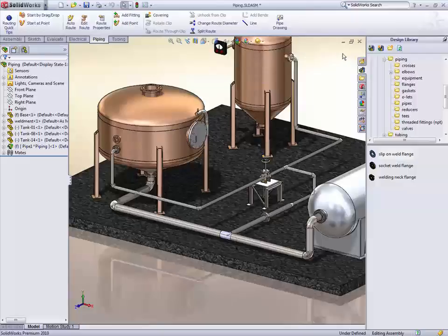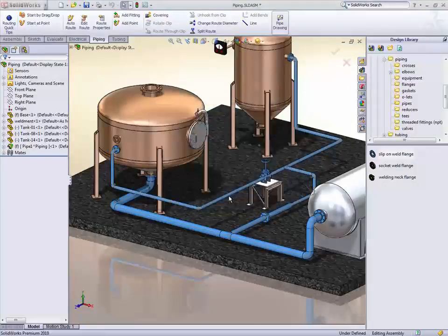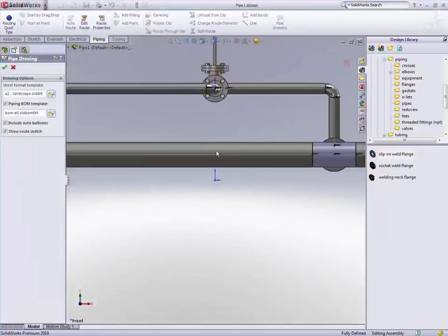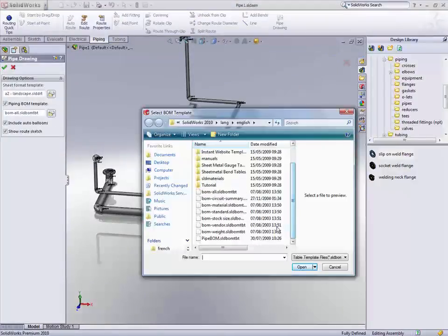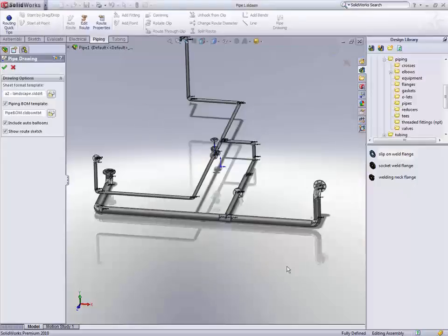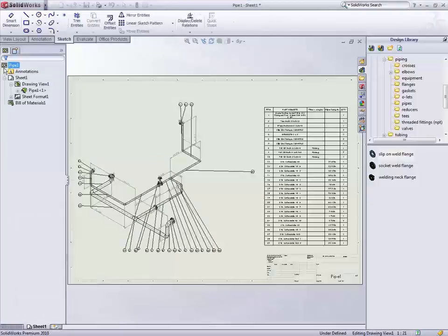Solidworks can put the details of a pipe route in a format suitable for creating a piping isometric drawing using alias isogen. For any other purpose than plant design, this solution is a little overkill. Many users just want a drawing of the pipe route, bill of materials and dimensions. The new Pipe Drawing button automates this process with a single button click. A little tidying up and the manufacturing drawing has been created with very little effort.